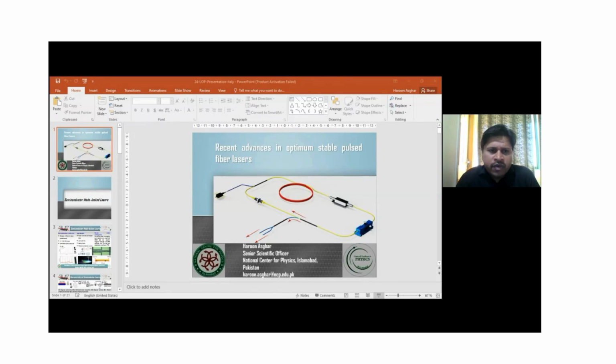The objective of the current study is that the ideal signal should be like this one, when the pulse is oscillating inside the laser cavity. However, in reality, the laser has some phase noise associated with it. This phase noise is also called timing jitter. The pulse train produced by a mode lock laser shows some deviation of the temporal pulse position from those in a perfectly periodic pulse chain, referred to as timing jitter. So the objective of this study is to minimize its phase noise and timing jitter, so that our laser could operate in an ultra stable regime.